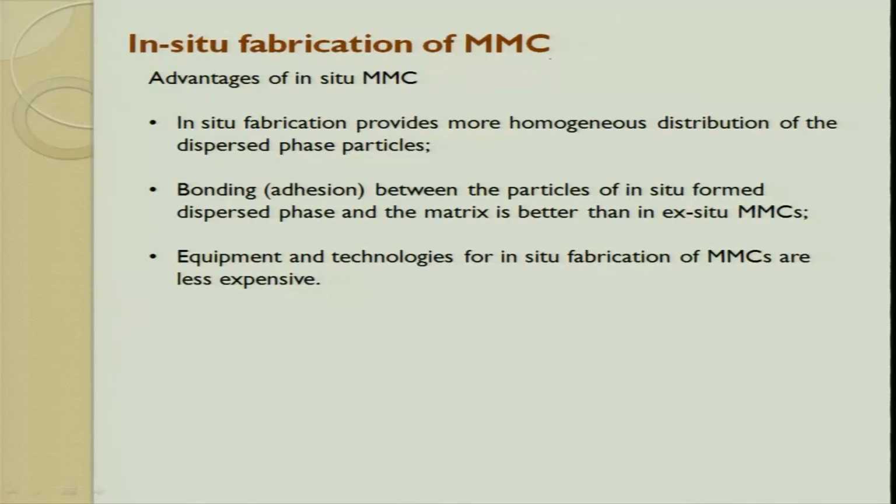The major advantage is that you can provide a more homogeneous distribution as compared to the others. The bonding is very good, and the equipment involved for making this is not so expensive like hot pressing; it is slightly more economical. But the biggest problem is that not everything can be done through this in situ fabrication method because of the material limitation.